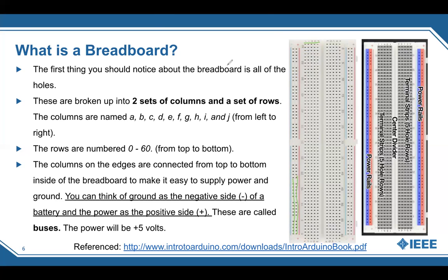Now that we've done that, we'll be able to talk a little more about what you can do with a breadboard and Arduino together. And this diagram's really nice too to see the bus row. So the negative is all connected here, and the positive is all connected in red. And then these rows are connected only by the row through those holes. Okay.